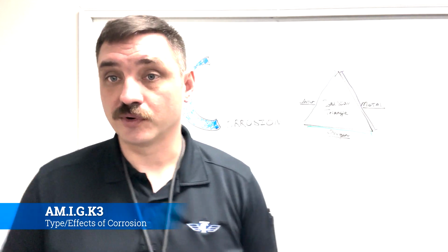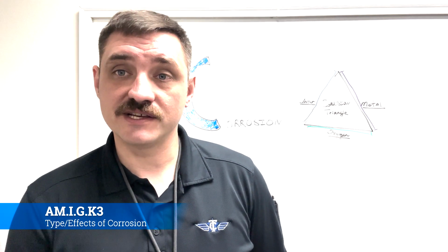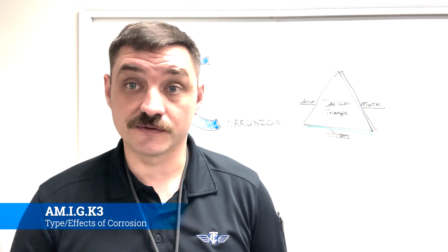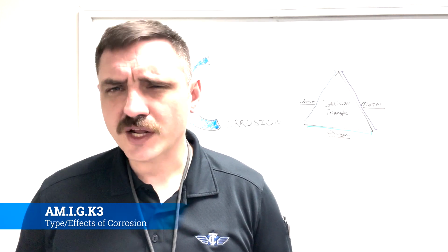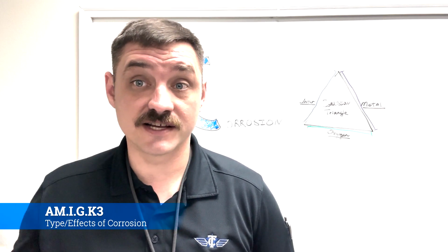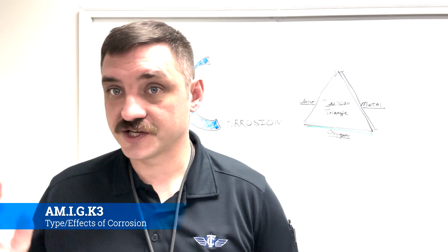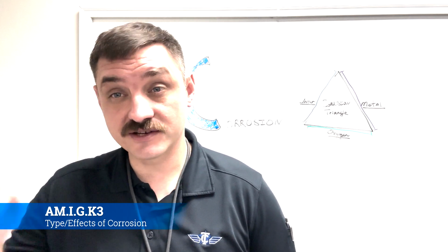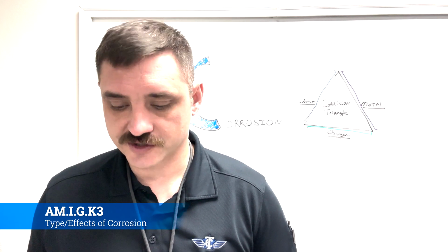You go over to Europe or the Northeast, you'll end up seeing those types of manifestations of corrosion. Aluminum will have this white powdery substance. That's how you know what corrosion looks like. If it's not shiny and it has kind of a gray haze over it, that's corrosion on the surface of the aluminum.